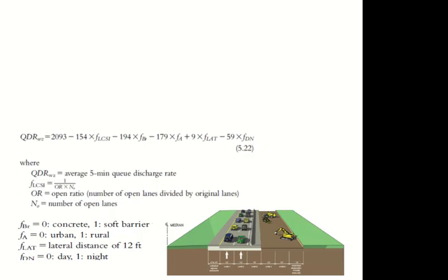Okay, there's another set of adjustment factors, CAF and SAF, for the work zone, which needs to be calculated. Up till now, I have shown you adjustment factors in the form of tables, but this one needs some calculations. What do we mean by work zone? Work zone means construction or maintenance work going on either on the highway or on the side of the highway.